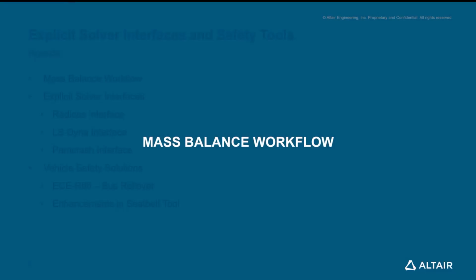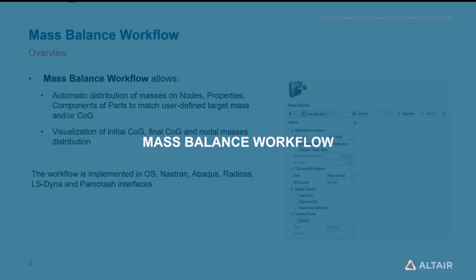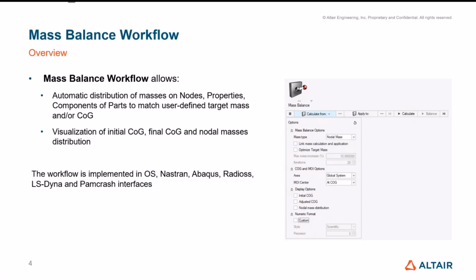So let's start with the mass balance workflow. The mass balance workflow was expected in HyperMesh for a very long time by many customers. So now it's available. We implemented it, as I said, not just for the explicit solver interfaces, but across multiple interfaces. It's implemented for OptiStruct, Nastran, Abaqus, Radioss, LS-DYNA, and PAM-CRASH interfaces.